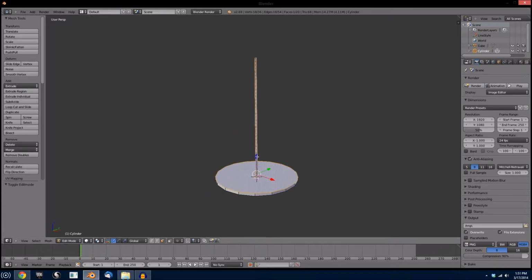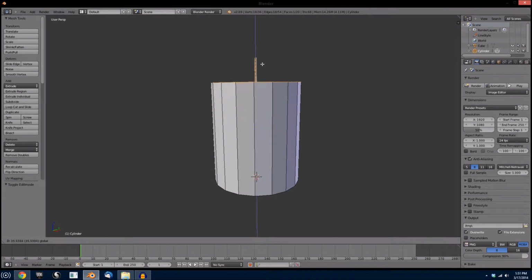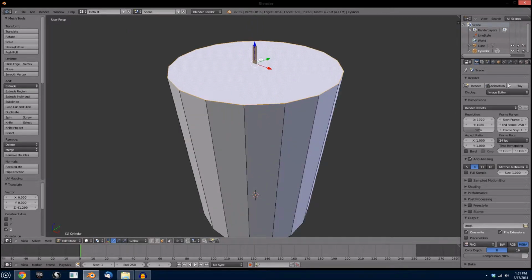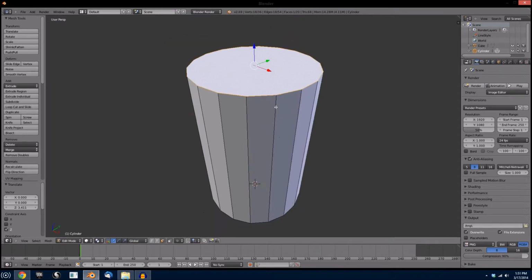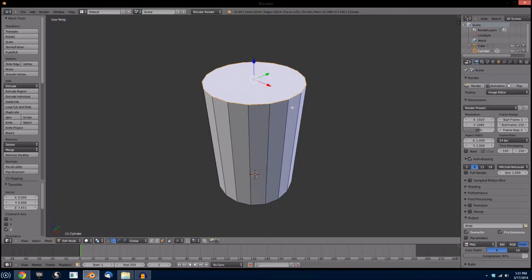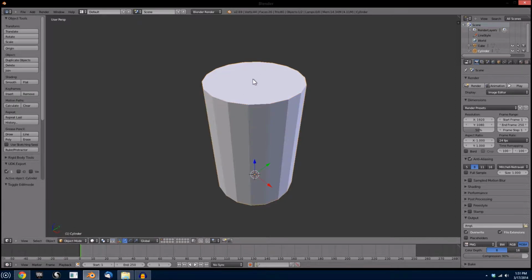Okay, we're going to just grab along the Z-axis using that arrow up to roughly the top of the yardstick. Makes it a little easier if you can actually see the yardstick, because what we're going to do now that we've got everything scaled is go into object mode, select that yardstick, and just delete it, because we don't need it anymore.